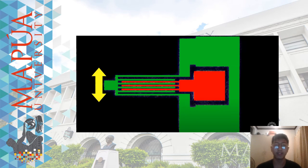Movement, vibrations, and even gravity can cause this little mass to move around, and when it does, it shifts the entire comb finger structure. When the fingers move, the distance between the fingers changes. And when the distance between the fingers changes, you get a change in capacitance.